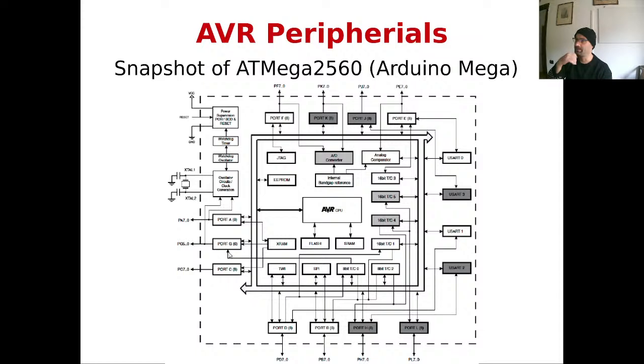This is just to provide you an overview. At the core of the chip, there is the AVR CPU, which executes the instructions, which are 8-bit instructions. Then we have a bunch of timers. We have an analog to digital converter to read data from analog components. For instance, you could build, let's say, a rather simplistic sound card with an Arduino.